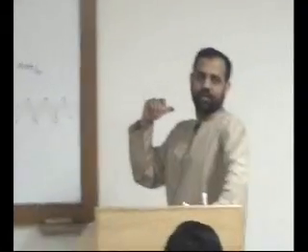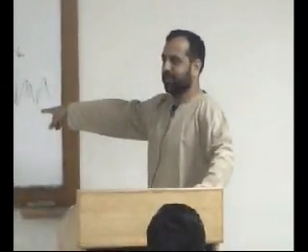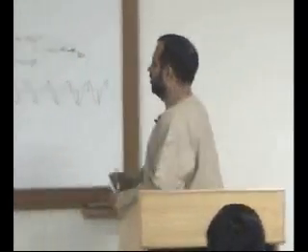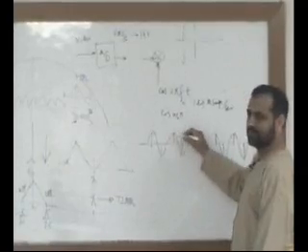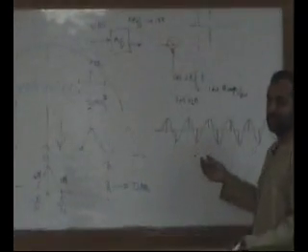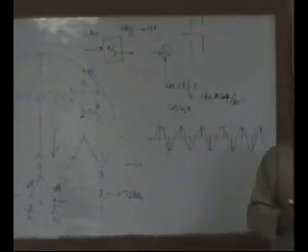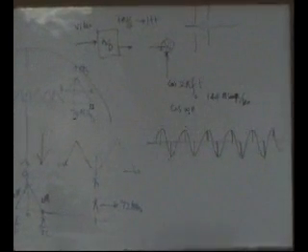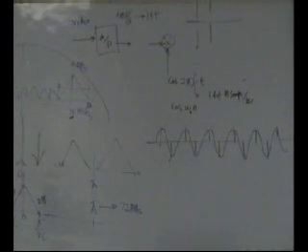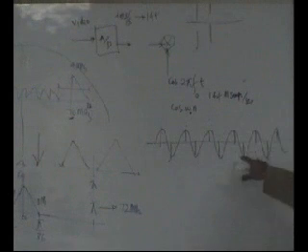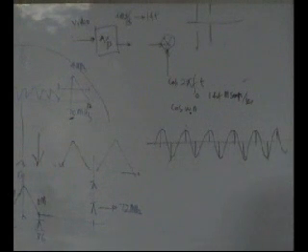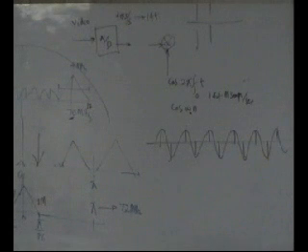Then you throw it on an A to D converter. So generating this is very simple. All you have to do is generate +1, -1, +1, -1, +1. This is really how you generate it. I mean, you need not compute cosine. If you are just generating this, you say plus, minus, plus, minus, plus, minus. You can generate at 140 mega samples per second. You can do it like this. So you can just figure out a way to generate this. Then you mix it, and after you mix it, then you throw it onto a D to A converter.